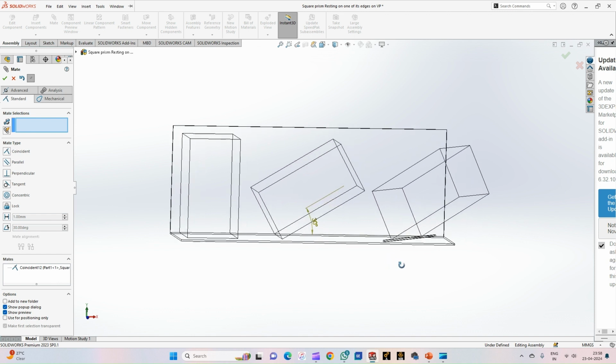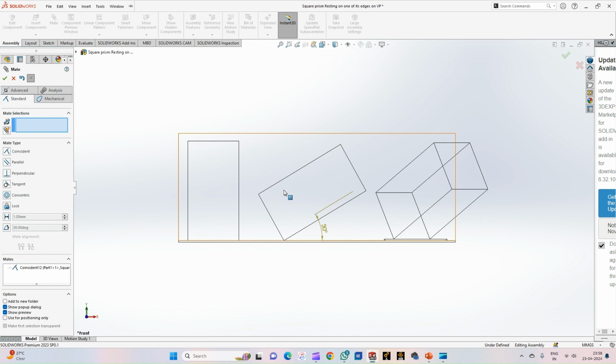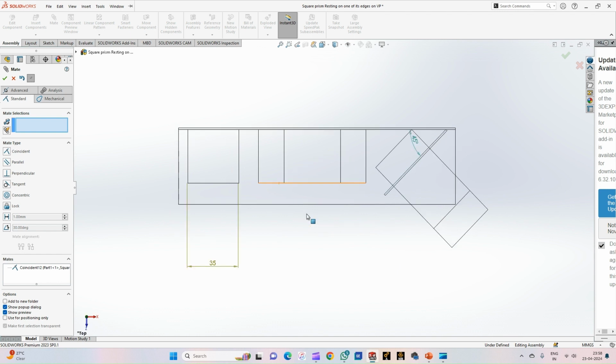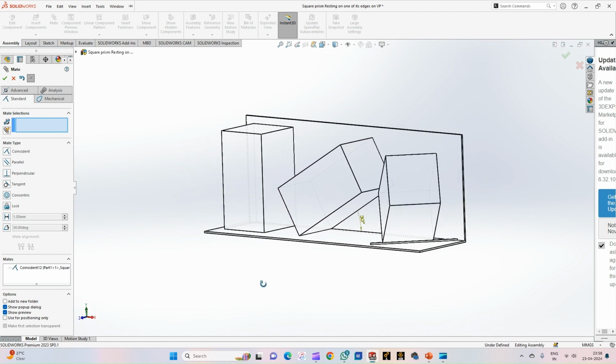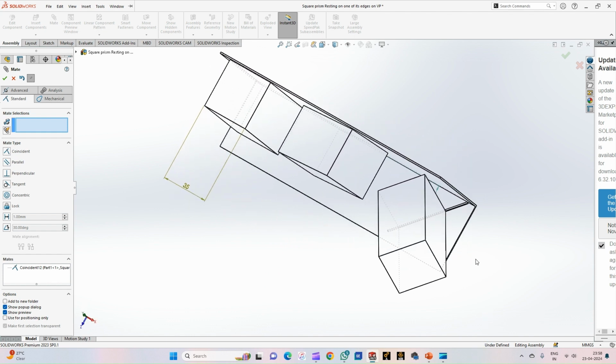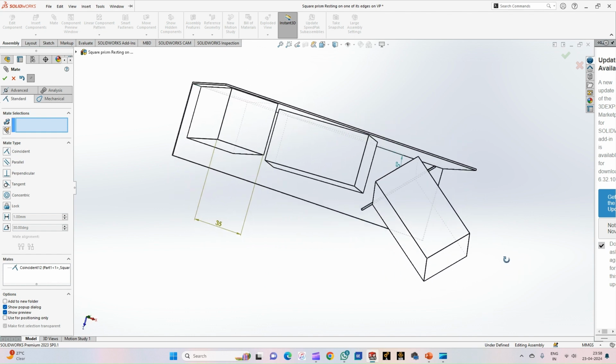Now this is the front view of the second position, and this is the top view of the second position, with the hidden lines. And now we'll go for the third position. For that, it says that the edge on which it is resting is inclined to VP at an angle of 45 degrees. You can just see that this line that I've taken for reference is inclined to the VP at an angle of 45 degrees.